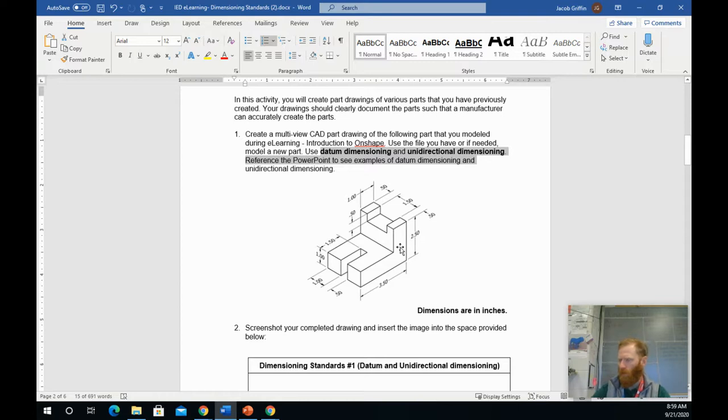So let's go back to our drawing and see where would be best to start from. So this looks like a large L shape laying on its side with a cut in the top and the bottom. So I would start from this right side face. Right here, extrude it a depth of 1.5 plus a half plus a half. So 2.5 inches deep. All right, that's where I would start. So let's start right down here at this corner. 3.5 inches to the right, 2.5 inches up, 1 inch back to the left. From there, we're going down 2.5 minus 1, so 1.5 inches, and then closing back out our L shape.